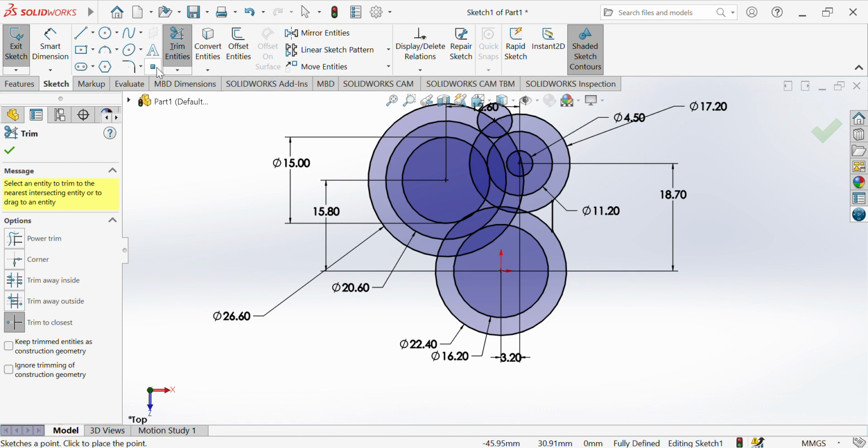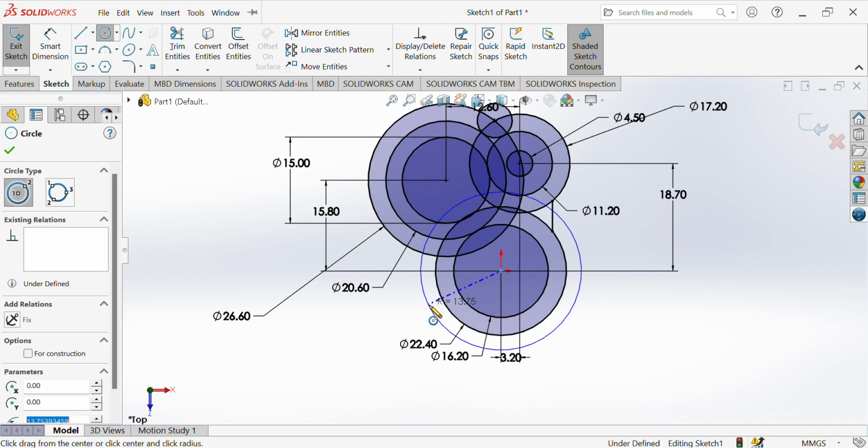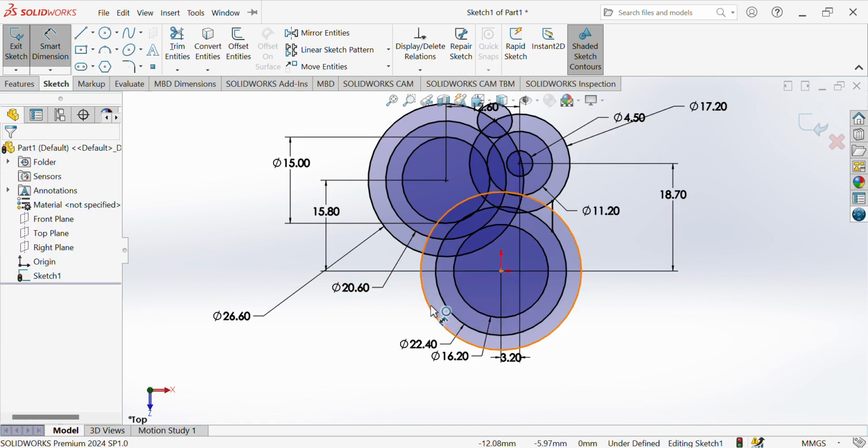So the next thing we have is, we'll do the same thing for this other side. So this circle is already set because it's still the same 3. The radius of this one is 11, outer one is 11.2. So plus 3, that's 14.2. Multiplying that by 2, that's 28.4. So you just draw a circle and the dimension is 28.4. Take your small dimension to 28.4.